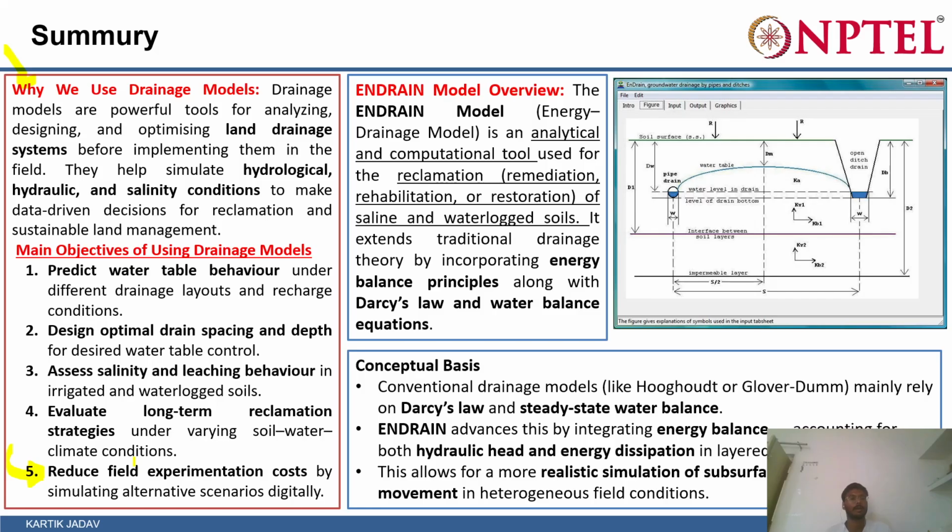And you can also assess the salinity and leaching behavior. Right? Suppose you have designed something, in that scenario, how leaching and salinity will be reduced. And of course, you play with the design, drain diameter, drain depth, and then certain filter media around the drains. So all these are changing aspects, and you can easily interpret or just get quick output by using this